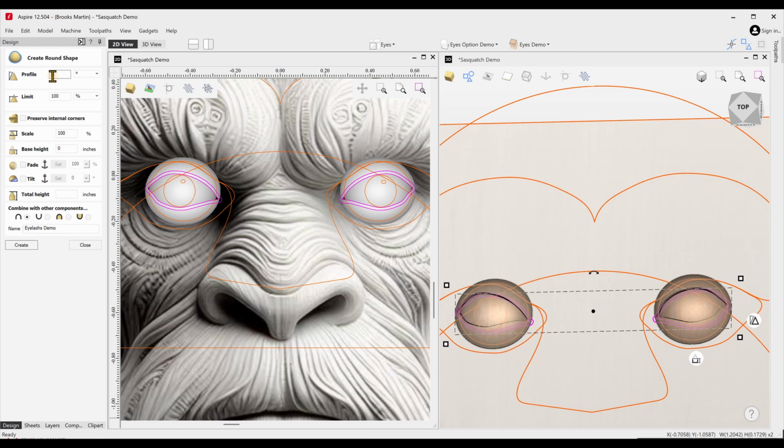And we'll give it some height, 22, and that turns out to be 1/1000th of an inch. That's not enough. Let's give it 41. Now it's 3/1000ths of an inch.